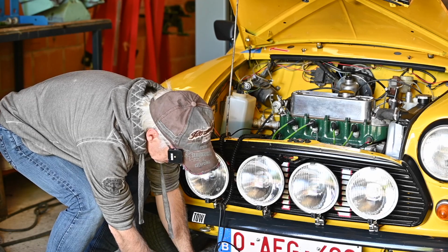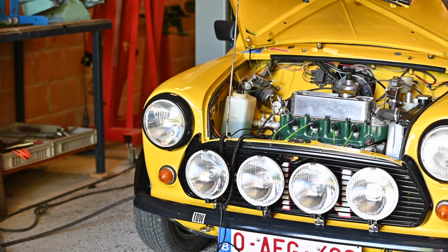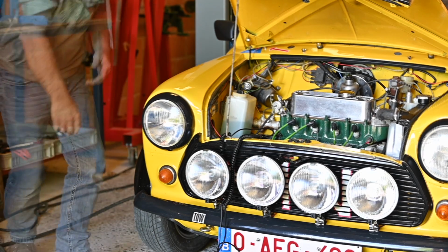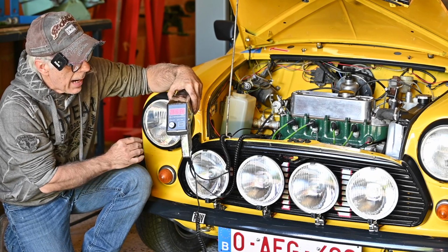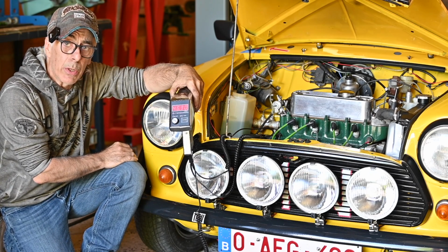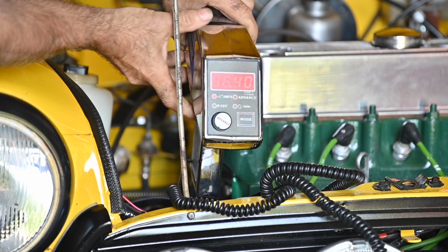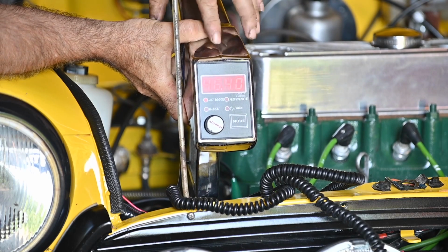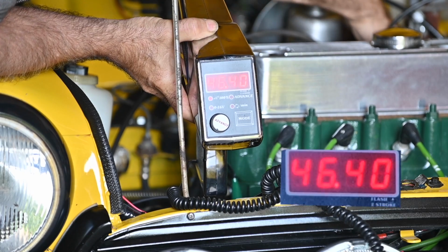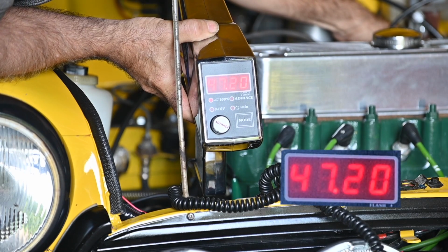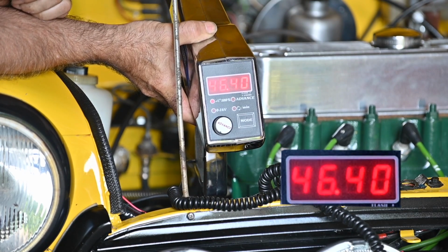So we'll check it as soon as the engine is running. So let me crank it up and see what happens. All right, so we got the engine running, and what I see here is that the dwell angle is around 46 degrees. That's exactly what we wanted. Here you have the actual dwell angle of the engine while it's running on idle, and you will see that it's not going to change. I have an angle of 46.4. It shouldn't change at all. It might change just a little bit. But that's very minor. So this is good. This is a proper dwell angle.